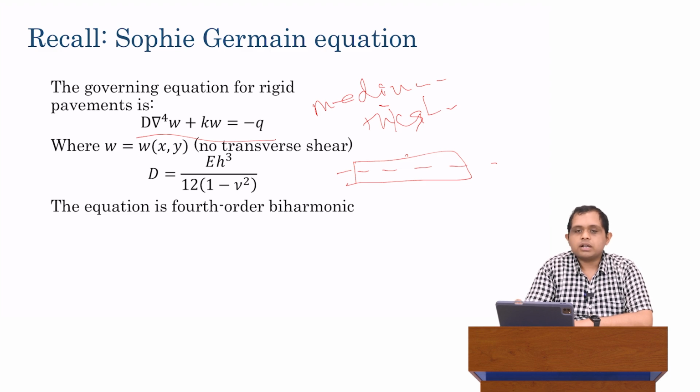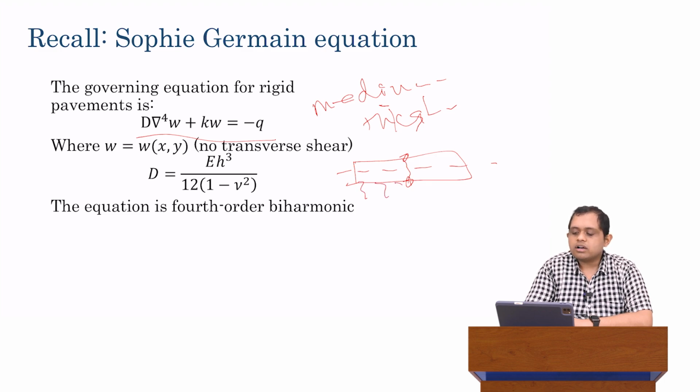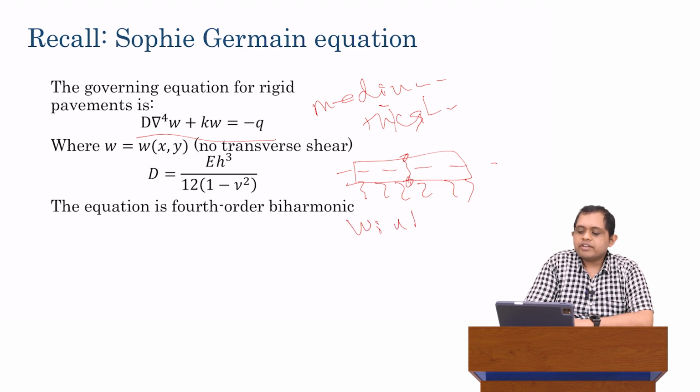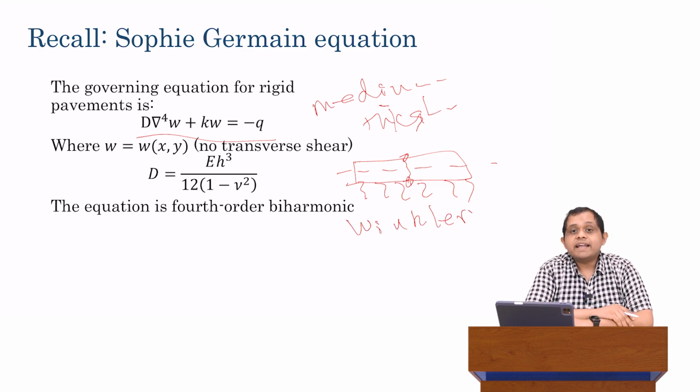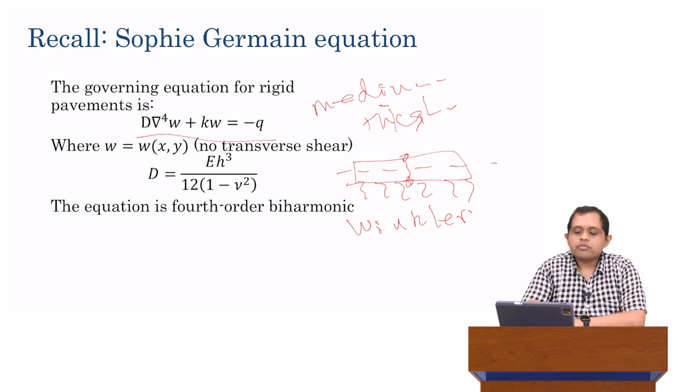So if I have a displacement vertically above the neutral plane, I'll have the same displacement vertically below, and along this whole line perpendicular to the neutral plane I'm going to have the same displacement throughout. So I am not going to have any shear strain or any transverse strain. Based on those assumptions, and a second assumption which we make for JPCP, the slab is sitting on a subgrade. The subgrade itself is modeled using what we call a Winkler foundation, sometimes also called a dense liquid foundation. So it's basically a bed of springs.